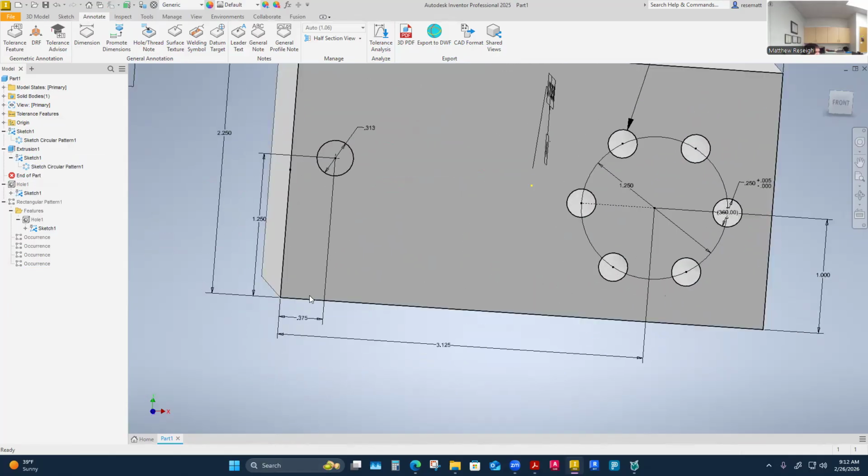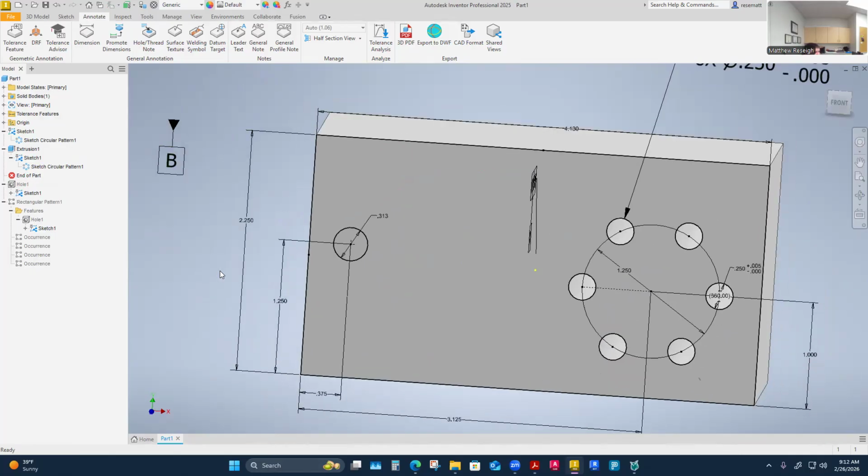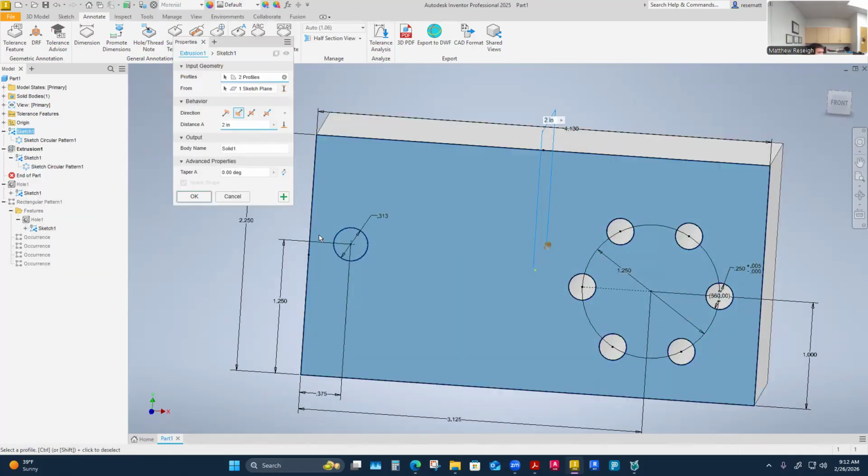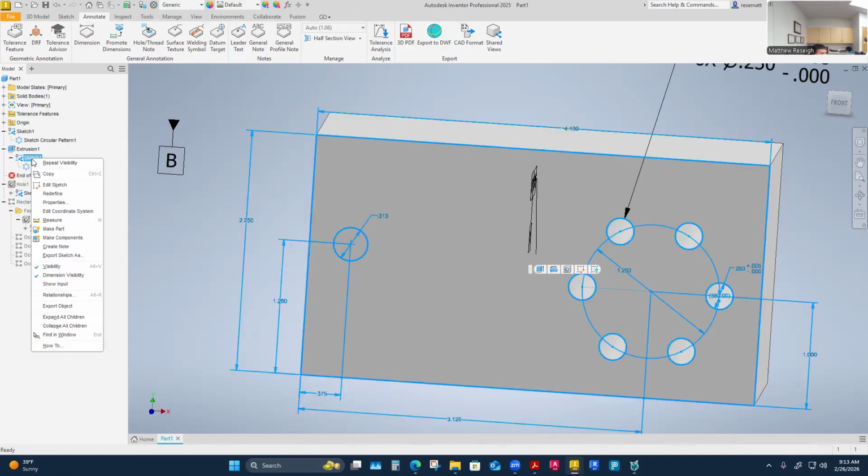Here I'm just going back in. Here's my sketch. I'm actually going to edit this extrusion now slightly. Edit my extrusion. I'm going to deselect this profile now. The problem is with this, I won't be able to pattern it, so I'll need to have done my hole. So I'm just going to cancel for a minute, go back into my sketch, and do my pattern in there like my other one. I'm just interested if this comes up.